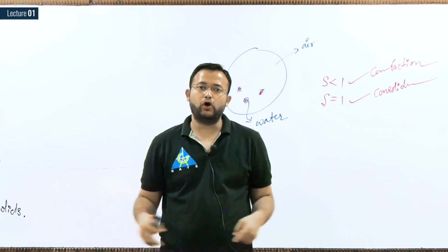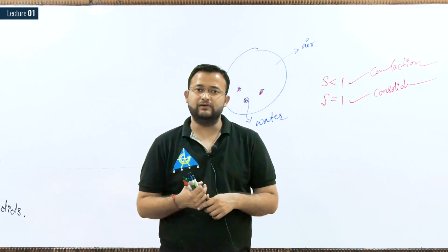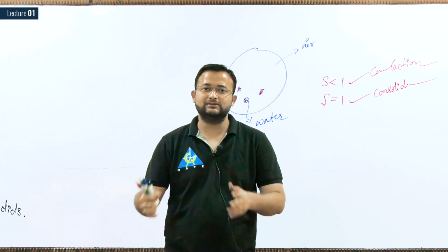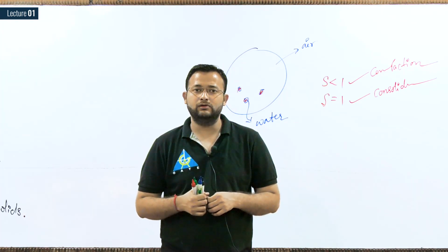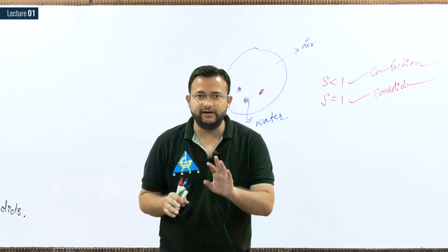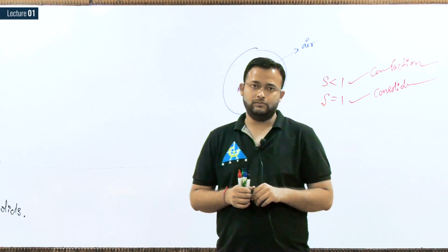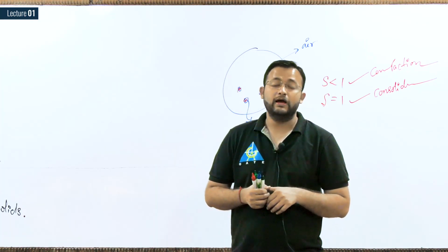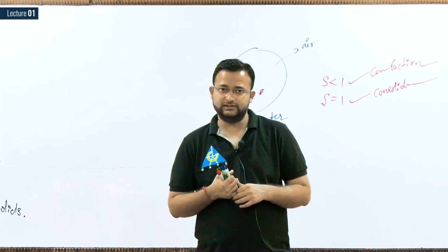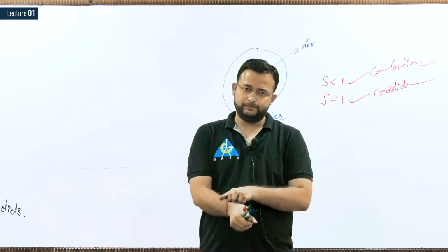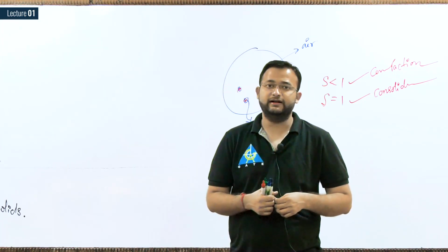Suppose I purchase one plot, will I wait for 100 years, because after 100 years consolidation will happen and complete water can be removed? No, I will not wait. I will perform the compaction, I will not wait for consolidation. Consolidation is a natural process, compaction I can perform. How the water will be removed naturally, that we can discuss.